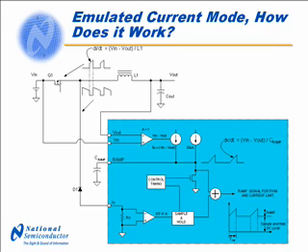When we study the characteristics of the buck switch current signal, we can note that the signal can be broken down into two parts, a pedestal and a ramp. When the buck switch initially turns on, the current level jumps to the same level that was conducting previously through the diode D1. By taking a sample and hold measurement of the diode current just before turning on the buck switch, we can establish this pedestal level. A small current sense resistor is placed in series with the diode anode to accomplish this measurement.